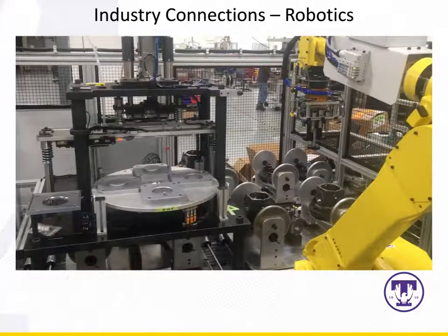So most motion that you'll see in an industrial machine, in industrial controls, is pneumatic-driven motion. That's what we see on this machine here. We see all of the motion being driven pneumatically, and when it's not pneumatic motion, typically that's because you need to have many positions that you're going to, not just one or two, or you need precise positioning, in which case you might use a linear servo.